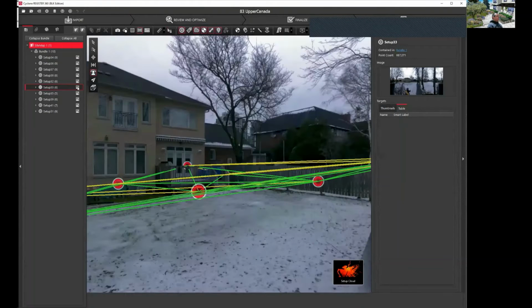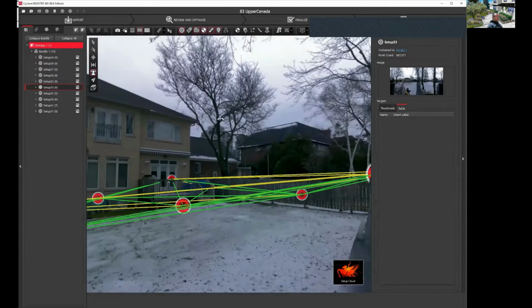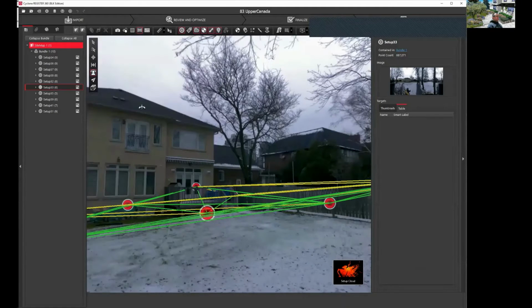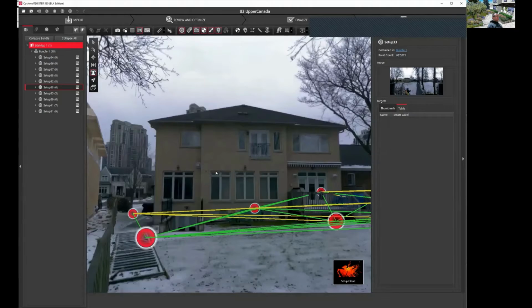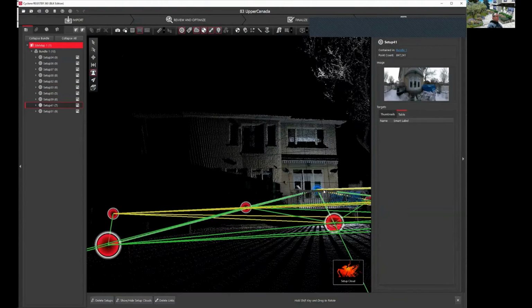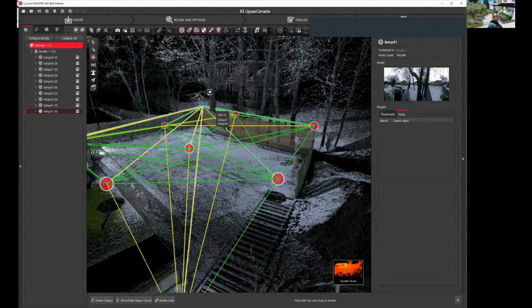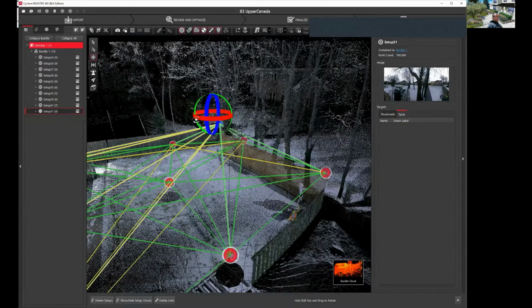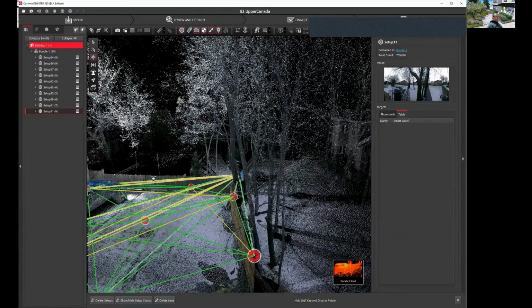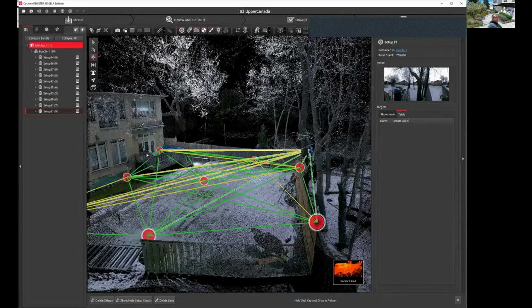Then I have high definition photographs 360 degrees from that spot. I also have laser accurate telemetry from that line of sight to everything it sees. I then take my little tripod and move it over about 6 to 10 meters. I play it again. I'll do upwards of 13 to 15 scans for a backyard.